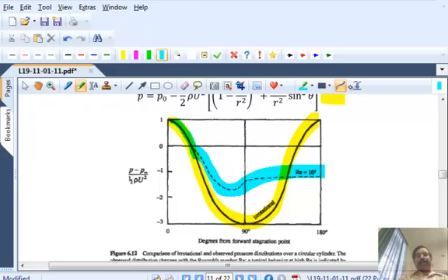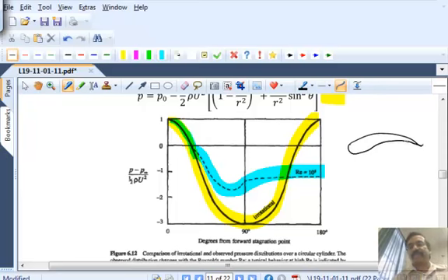But for any other shape of the object, you will find a net pressure, okay, a net force. And in fact, the place where this is used most often is in aerodynamic objects. If I have a plain wing like that and I integrate this pressure distribution around it, I will get a net pressure that is non-zero, and I can get the direction of the net pressure, and that would be the lift force.